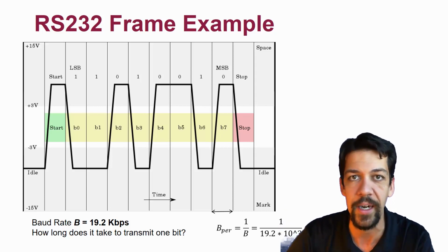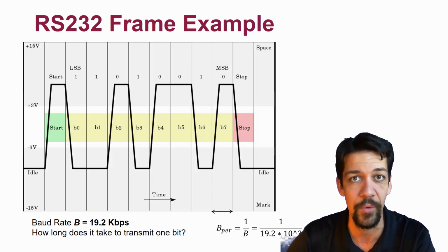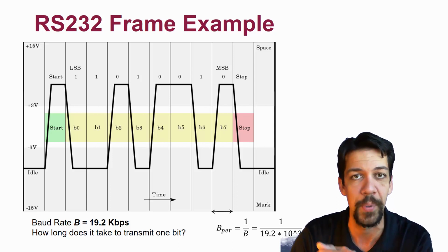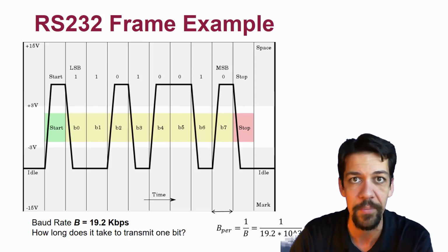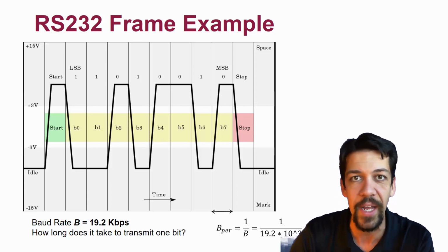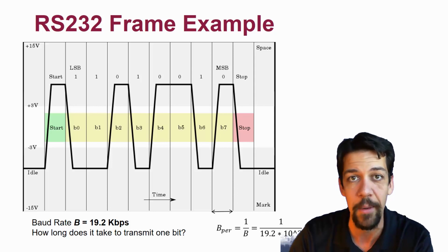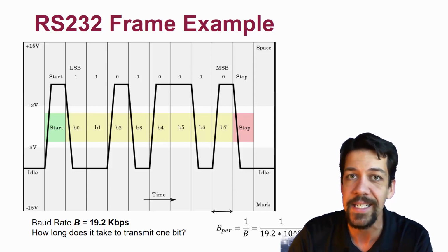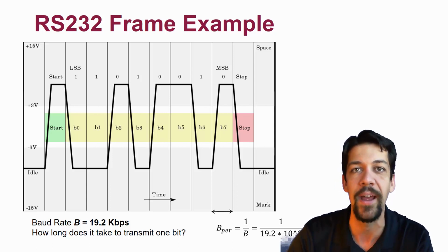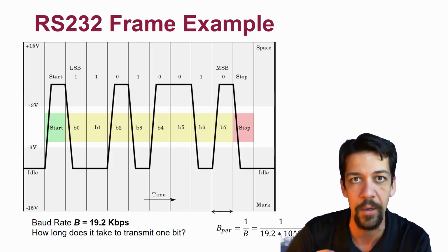The advantage here is that if we both publish the same protocol, if we both say, I'm going to participate at 9600 bits per second, then any device that's able to handle 9600 bits per second will be able to listen and communicate with messages over RS232 at that baud rate. So it's really easy to set this up, but we have to have very precise timing hardware on both ends.